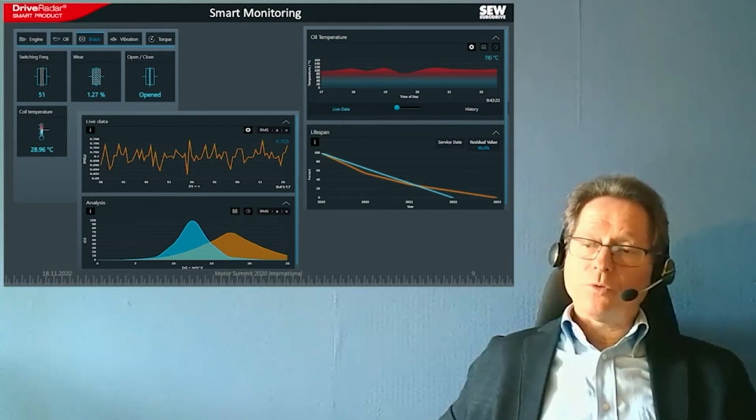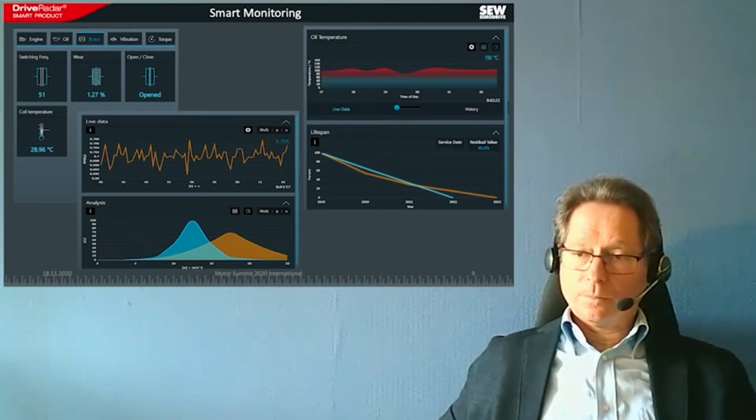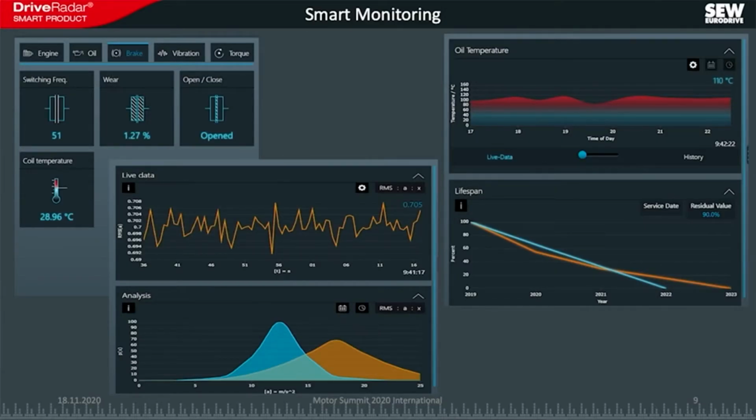We also observe the vibration. We process the data with different mathematical tools like kurtosis. Here you see the evaluation after the startup of the motor, and here maybe 1 or 2 years later. So you see a difference. Maybe your motor has a bearing damage.